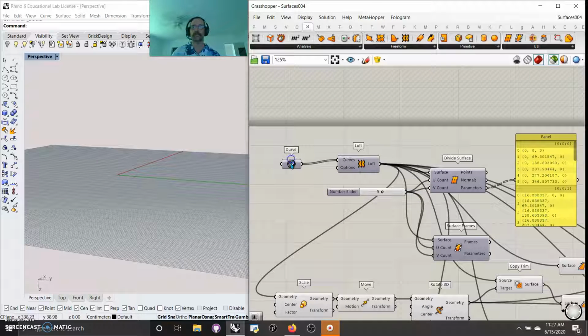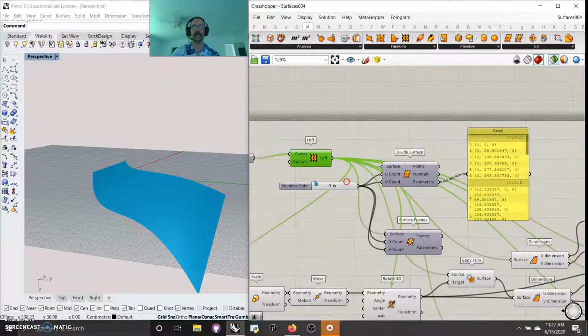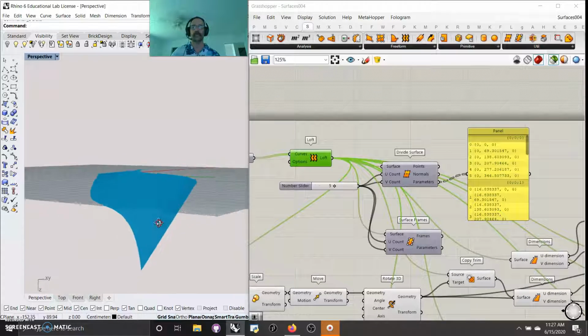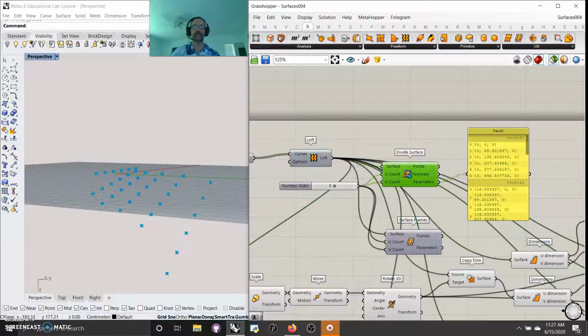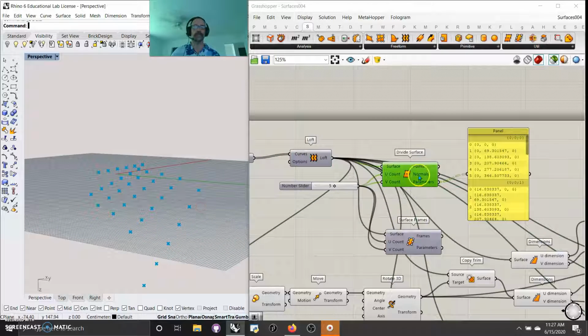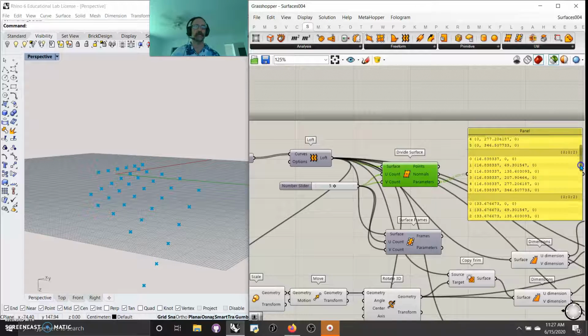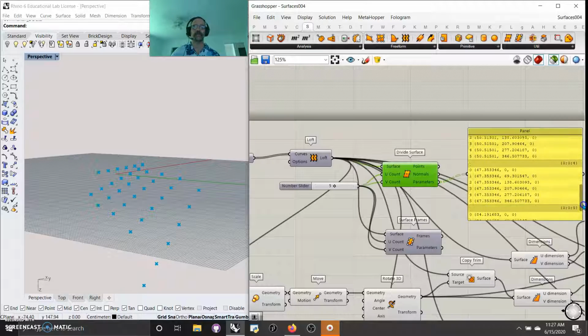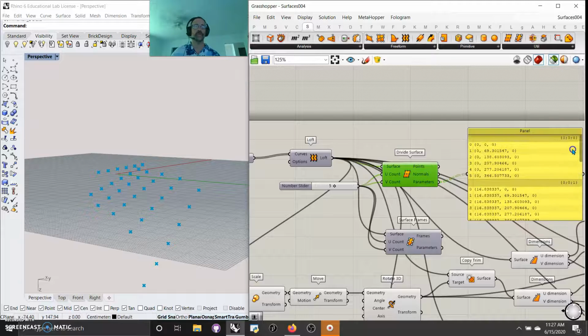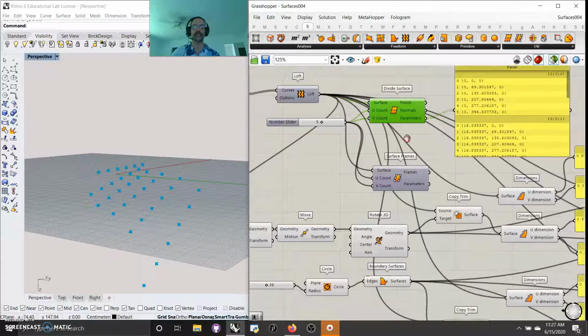So all I did was take some lines, I lofted them. I have a surface that's not planar. Basically, I've divided that surface up into its points. That's it. You get your normals. You get some pretty cool parameters of where they are situated in there as a UV point. As points, and then the parameters of where they actually are, which is nice. Have a look through there, and they've been grafted into each row, so you can flip matrix. Say you wanted to interpolate those curves in another direction. You get your normals and you get your points.